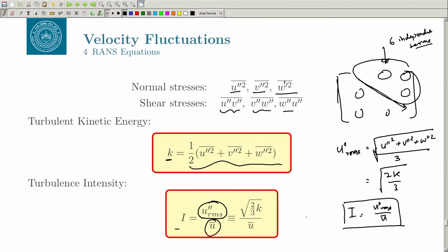It can be a very quiet tunnel, where the turbulence intensity can be very low, maybe 1%, 0.1%, 0.5%, or it can be a noisy tunnel where the intensity can be very high, maybe 5%, 10%, and so on. Once you know the intensity, you can use that in the model to find different terms, including the turbulence kinetic energy, dissipation rate, and hence the stresses.